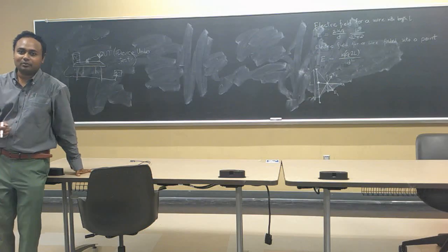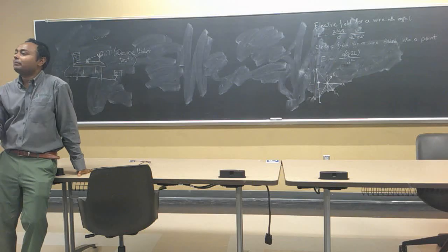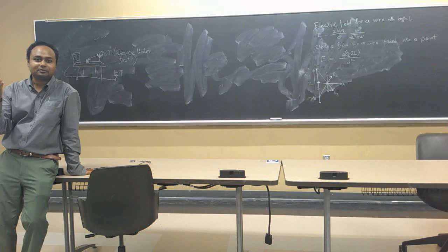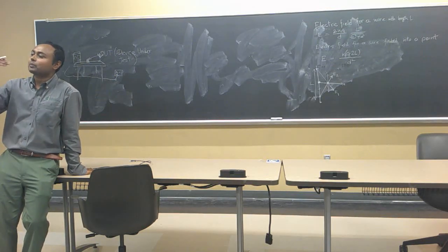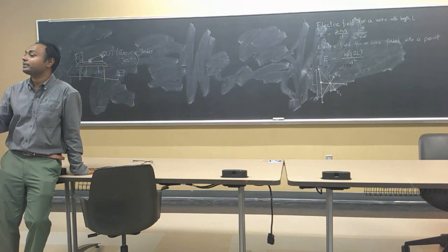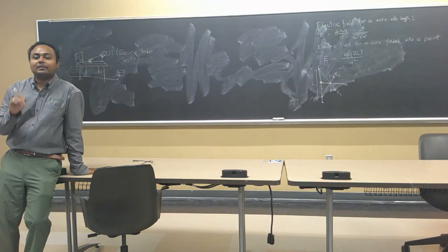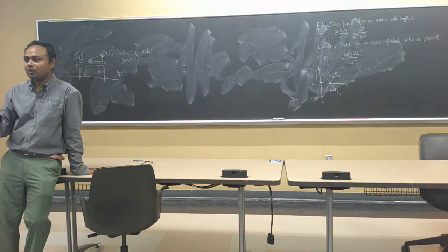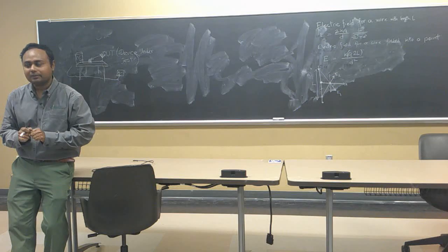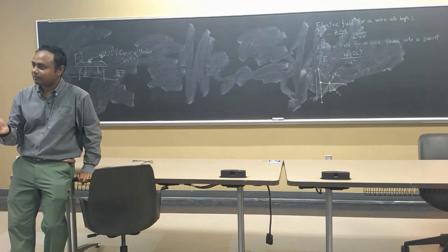Whatever is closest. Right. Whichever is closest. Right? That's the very first guess you should pinch on. Whichever is closest might be the biggest source of interference. And why do you think that the distance matters? So it's proportional to 1 over d squared. Right. So Coulomb's law says that it is proportional to 1 over d squared. And that's why if something is closer to my duct, it probably has the biggest impact. It probably is the biggest source of noise. But we learned two different things. We learned that force could be proportional to 1 over d, or force could be proportional to 1 over d squared. If it is a point source, then force is proportional to 1 over d squared. If it's a long wire, then force is proportional to 1 over d, right? So it changes.